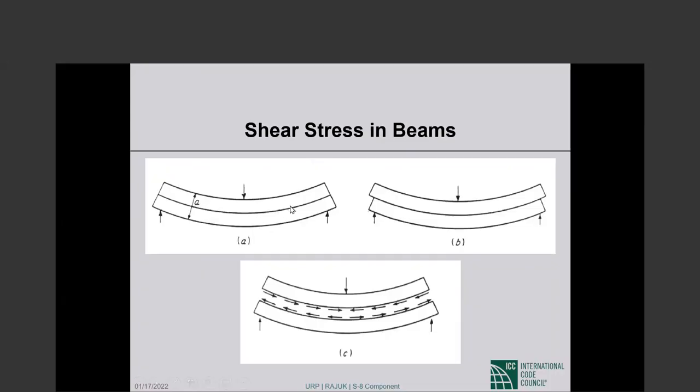So when the beam bends like a one-piece beam, a normal beam, the glue must be applying shear stresses as shown in this picture on the upper portion, shear stresses that are trying to shorten or bring the upper portion back in, and shear stresses on the lower portion as shown by the arrows, which are trying to drag the lower portion out.